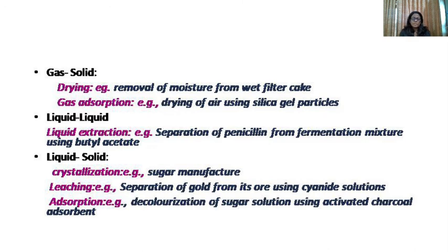Coming to adsorption, we have one application here: how sugar solution is decolorized using activated charcoal as adsorbent material. Here the contact is between a liquid solution and solid adsorbent particles. Since the concentration of certain substances from a liquid can occur on a suitable solid adsorbent, we can contact the two in a suitable manner so that the required component is separated. The sugar solution you get at the end is impure with some color substances.